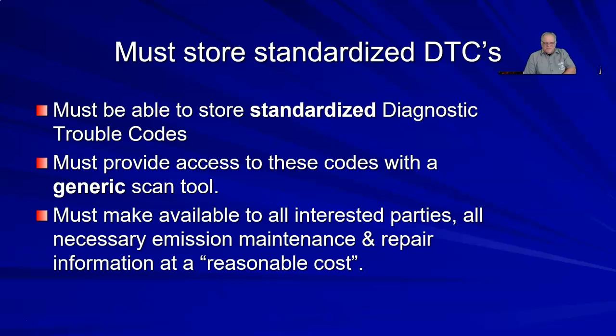Keep in mind, if you go and get an OBD2 scan tool, this is only dealing with emissions. It's not going to talk to the computer that's managing the HVAC system. It's not going to talk to the ABS computer. May not be able to talk to the transmission computer if that's a separate one.